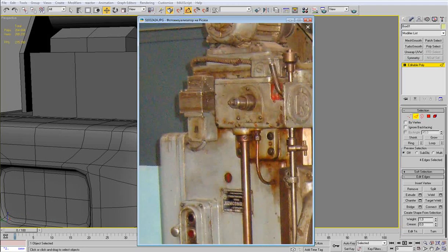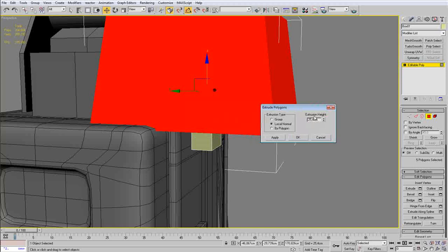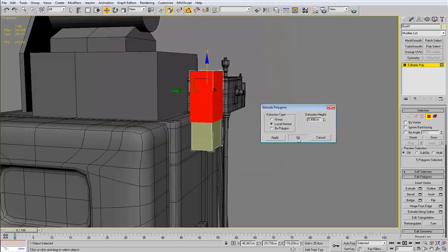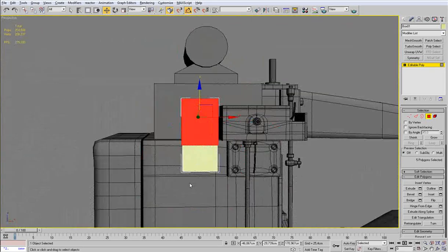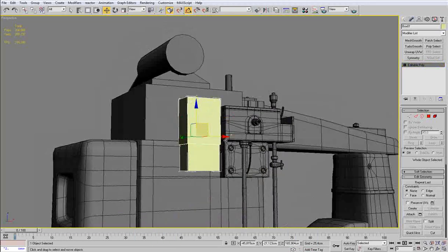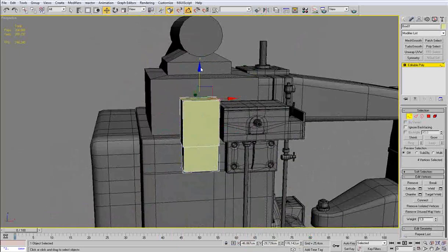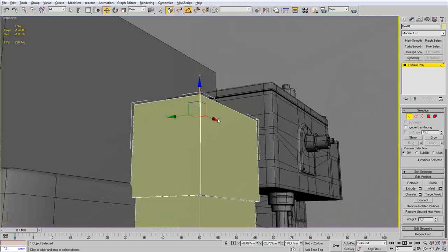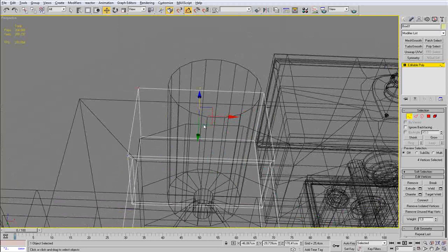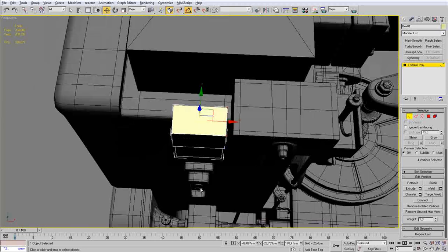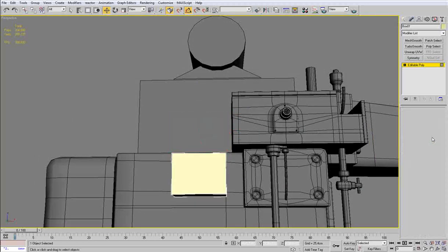So I start here by making a connect and position it down a bit. Then I select all of the top polygons and make a small extrude on the local normals. Okay, so now I'm just going to bring those vertices down. Just looking around to get a feel for the shape and the proportions.